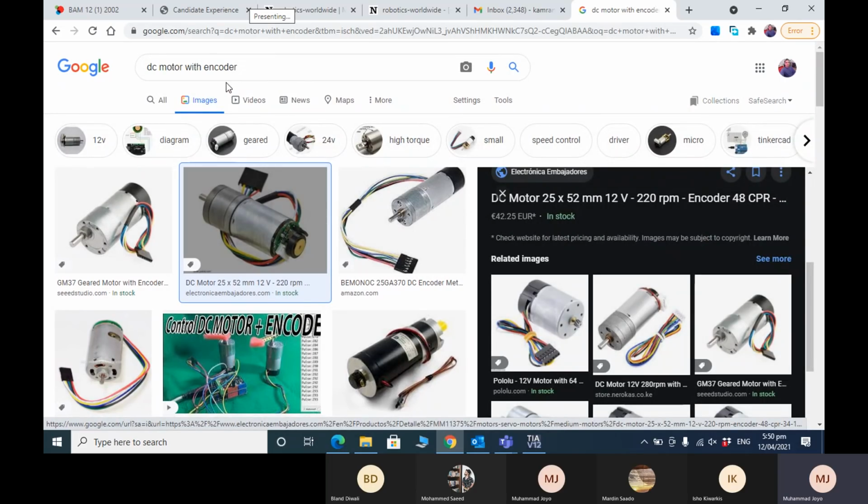If channel A is high, if channel B is high at the time, based on that, the controller knows if the motor is running forward or backward, or if the counting has to be done in a positive way or in a negative way. So basically, it is an incremental encoder. Okay, there are other encoders as well.